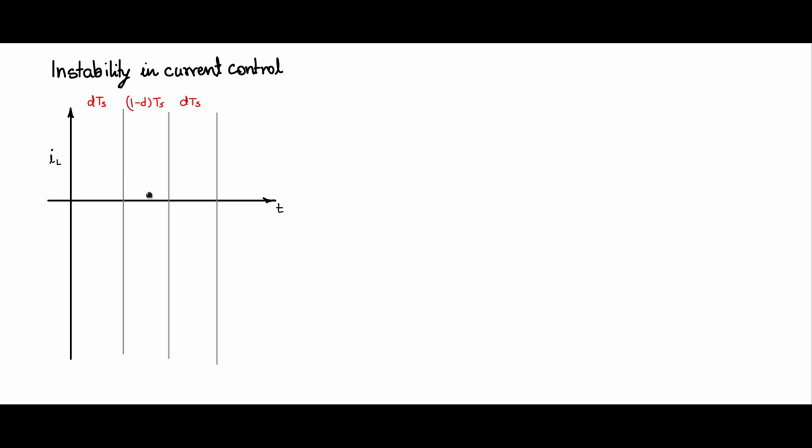Now this is the current that we need to study. So let me draw this average inductor current, which is I0, and let me superimpose on that the actual inductor current, which will be in this form of a linearly rising, linearly falling wave shape. So this slope rate is the voltage across the inductor during the dTs period divided by L, and the voltage across the inductor during the (1 minus d)Ts period divided by L. But I am going to use generic slope terms.